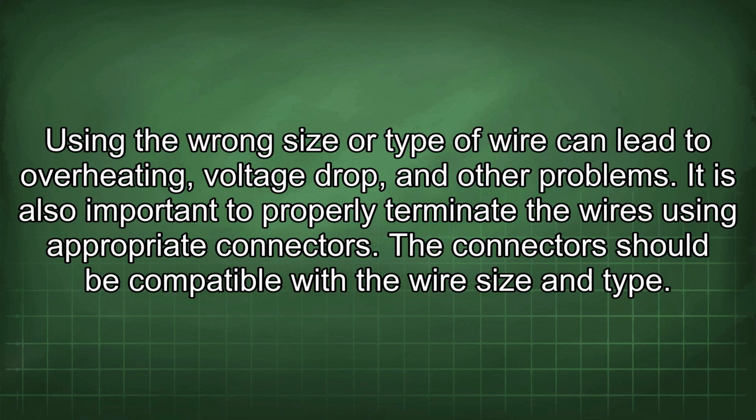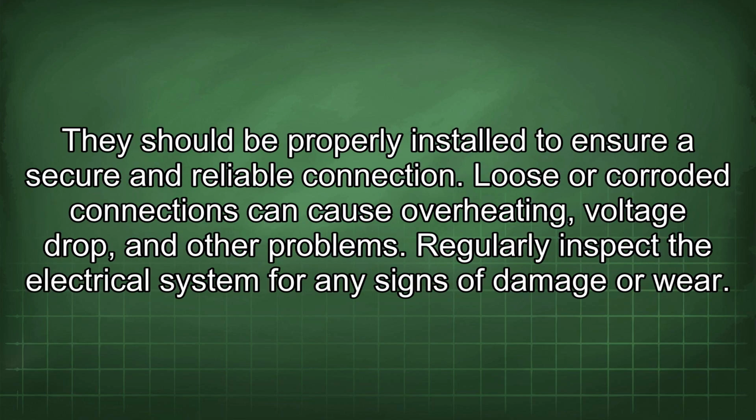It is also important to properly terminate the wires using appropriate connectors. The connectors should be compatible with the wire size and type. They should be properly installed to ensure a secure and reliable connection. Loose or corroded connections can cause overheating, voltage drop, and other problems.